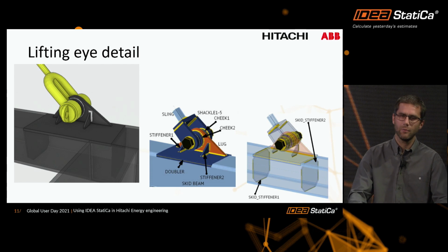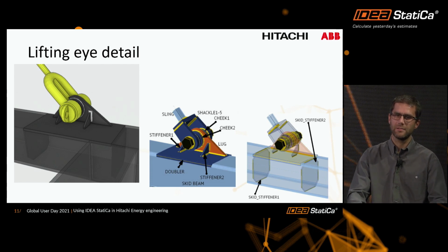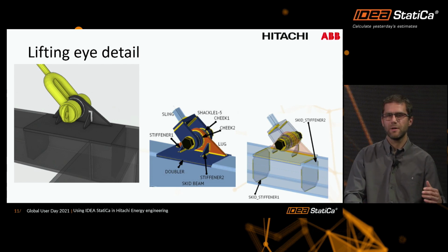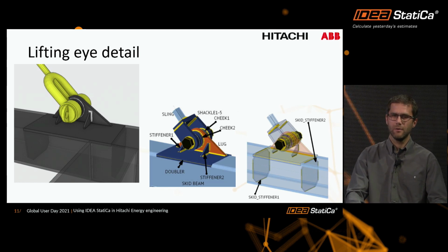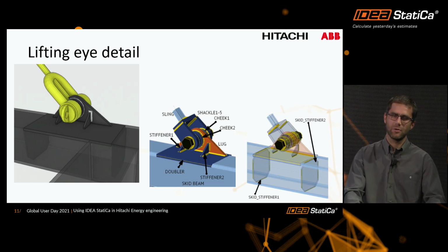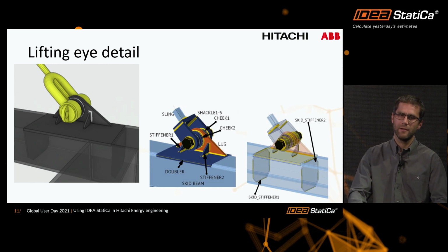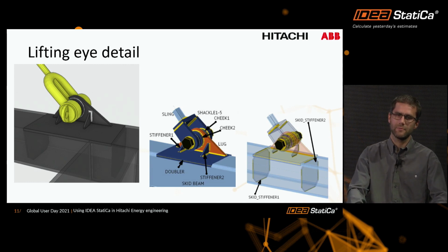The final one looked this way, that we cut only the upper part of the square profile. We replaced it with a plate of a bigger thickness. Because we opened this profile, we were also able to provide some inner stiffeners, which definitely helped as well.